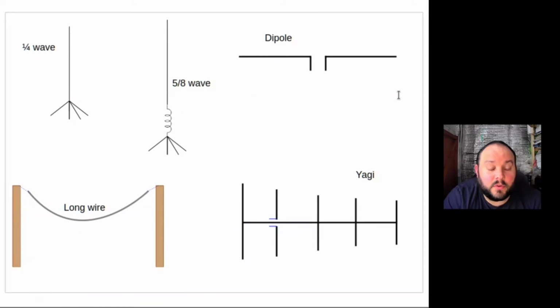This gives the effect of a much better range in both transmitting ability but also receiving ability. The downside is that if you're trying to listen to the whole area that you're in, you'll not be able to hear very well in any direction other than that at which the aerial is pointing. There are many other designs of aerials, and if you're interested in learning more about them, I'd highly recommend joining your local radio club.